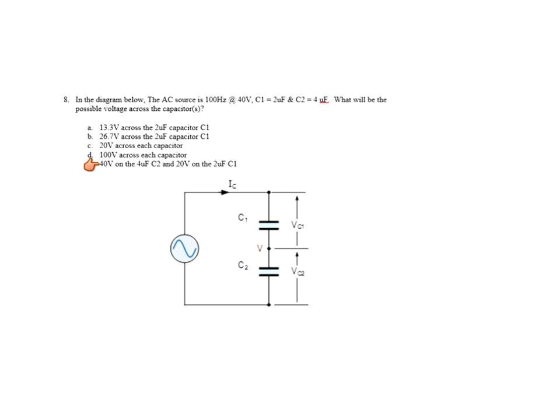40 volts on the 4 microfarad and 20 volts on the 2 microfarad. No, because 40 and 20 is 60. I only have 40 applied. Plus, this shows a smaller voltage on the smaller cap, which is not right. The only possible answer here would be B, 27 volts across the 2 microfarad. Why? The 2 microfarad is the smaller cap. It's going to have more than half of the voltage in this case. So watch for that.